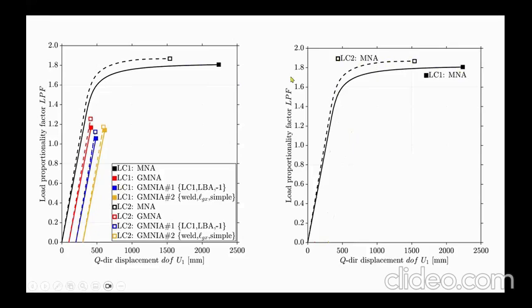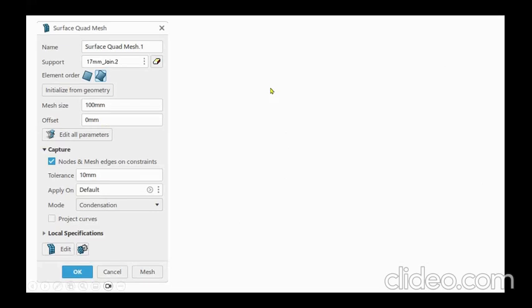Now, when it comes to meshing, because these are six joints that I have to mesh for each, the layers with the same thickness, I'm going to use parabolic first of all, mesh size 100. These are the same numbers that the YouTuber is using. And because at the interface of these joints there will be maybe duplicate nodes, I have to merge them.